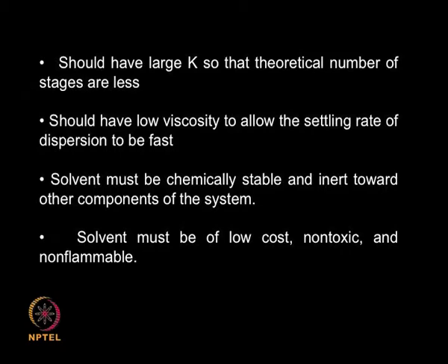Now, the K value has to be sufficiently large. K is nothing but the partition coefficient. If the K value is large, then you will have fewer theoretical plates or theoretical stages. If the K value is small, I need to keep on doing the extraction many times. We have looked at many problems, both the counter current, co-current, cross current systems, and there you have realized if the K value is very small, I need to keep on contacting both the solvent layer and the heavy layer in many stages to achieve an efficient separation.